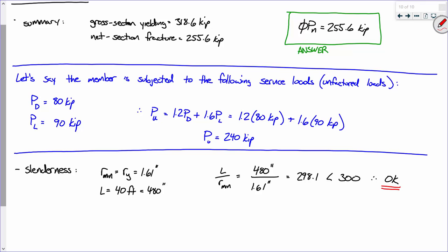Does RISA calculate multiple members like this and give you an idea of which one? Yeah, it will. The question you're asking is very loaded. So let me answer it a couple different ways. Do you remember in RISA when we would specify these basic load cases, and then at the very end when we did load combos, we would just say basic load case 1 and a load factor of 1. You remember that? Well, what we would really do if we were analyzing a full-scale building is we would have a load case with the dead loads and a load case with the live loads and then the snow loads and then the wind loads. And then RISA already has a lot of these load combos built into it, so you can just hit go and it'll do all of this factoring for you.